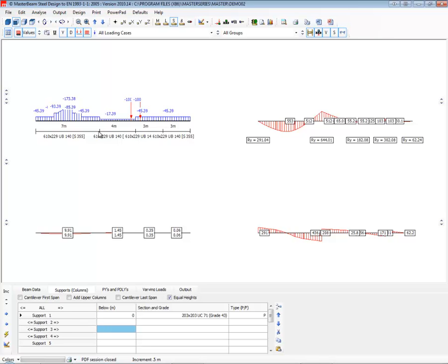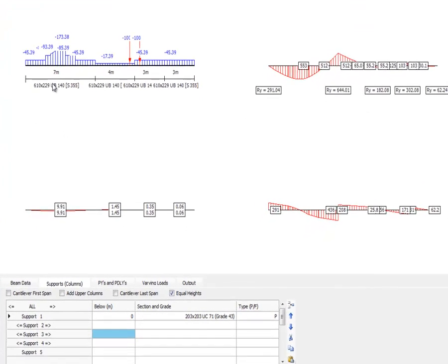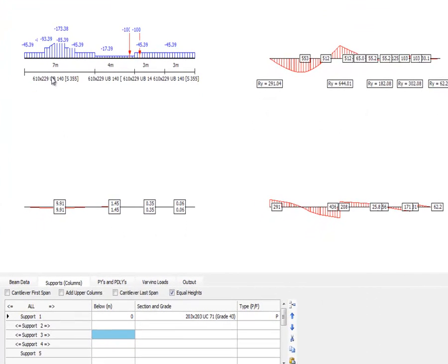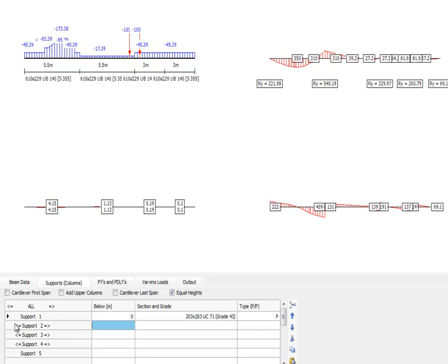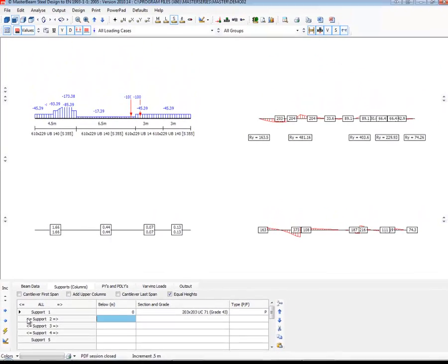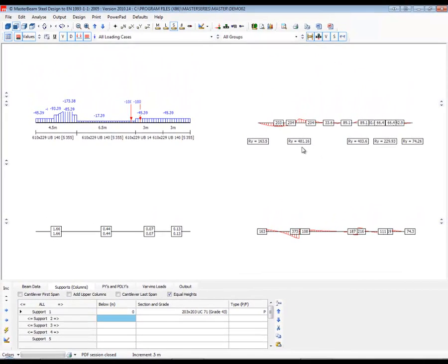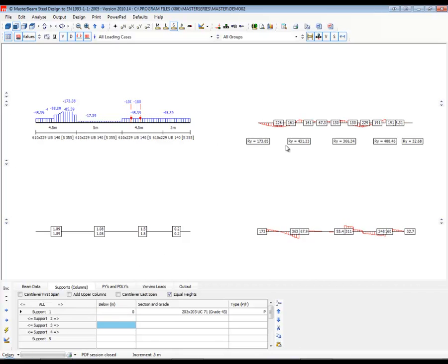So we're getting a sculpted and modelled set of bending moments and shear forces and reactions for where our new location is. And that can be quite handy if you're doing a concrete beam, which we will do in a moment. And in this concrete beam, you're trying to work out pile loads and reduce pile loads where you have to. I could, for example, say, well, actually, if we pull this across, then we might get a reduction down below 500 for our shear, our reactions. So now the reactions below 500, and we could even just pull this one over again to balance it out and make it more balanced.